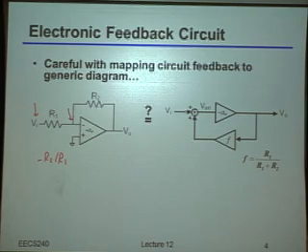What you actually did, you go through an attenuation block first, right? So in particular, let's redraw the block diagram now. What is that attenuation factor you go through? What's the value of that attenuation? Yeah, exactly. It's just R2 over R1 plus R2, which, by the way, is of course just the resistive divider in the other direction, right?